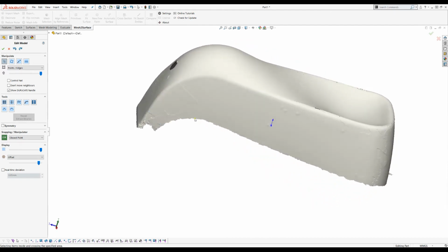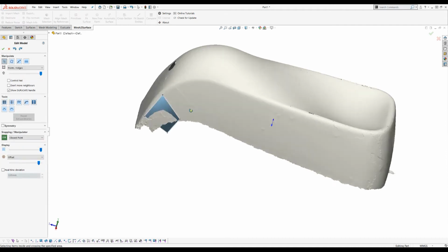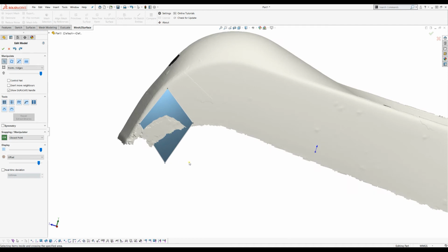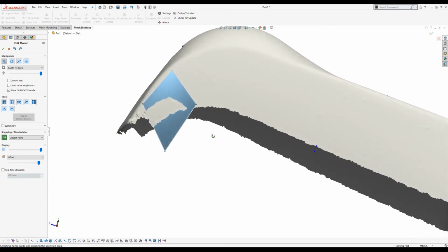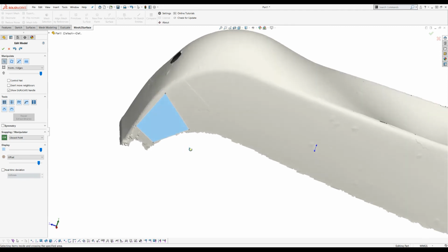I will undo again and start, and we'll click on the mesh, outside the mesh, and here. So what happens now is that when you create your face, when you click, if you don't click on the mesh, it does a ray tracing. I mean, from the viewport, it tries to hit a mesh underneath, and if there isn't, it just places this point somewhere in space, which in our case is not good enough. So what I need to do is just take this point, drag it, and drop it on top of the mesh.